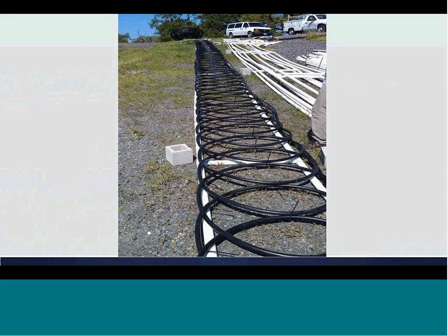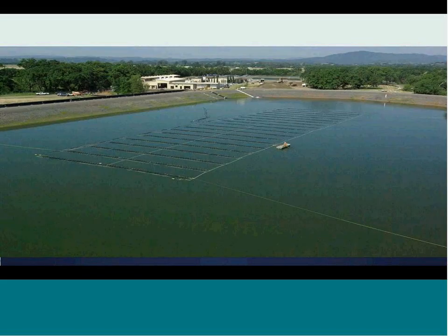Here there are about 16 of these slinky loops lashed together on this PVC frame. And basically, at this point, if you're a loop contractor or mechanical contractor that's going to be installing these types of systems, it's totally acceptable to procure a rowboat because you're going to need it to get out into the middle of the pond and get it coordinated and organized for sinking. The next step after this would be to, like I said previously, fill the loop up with water and allow it to sink.